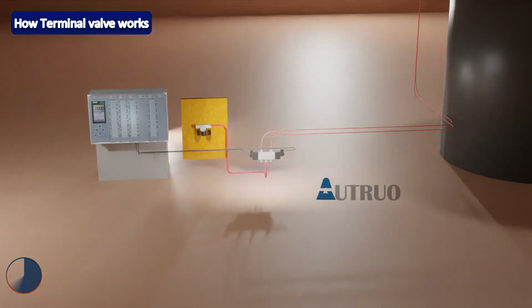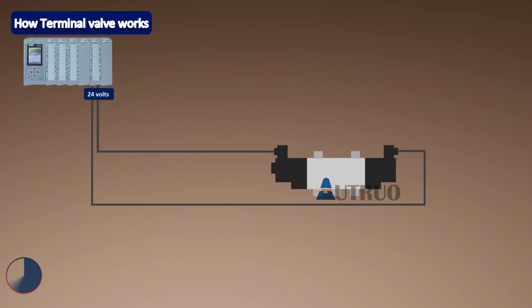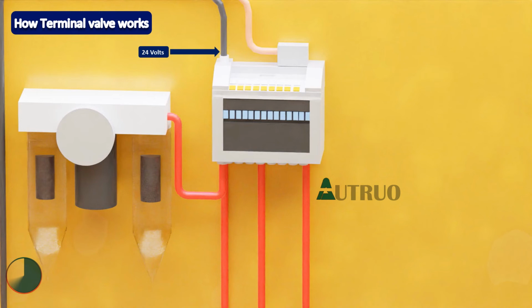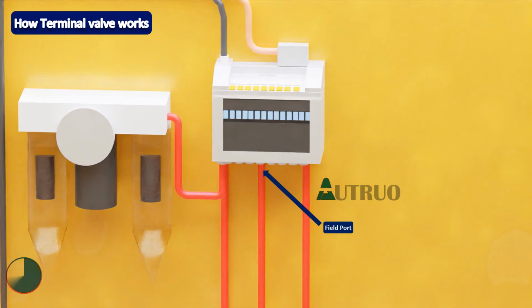Now, unlike the electro-valve that requires a dedicated 24 volts signal for actuation, the 24 volts that is connected at the input will be shared between the channels and hence, the field device will be actuated with compressed air. The good news is that multiple channels can all be actuated all at once. Now this type of device comes with some unique features.